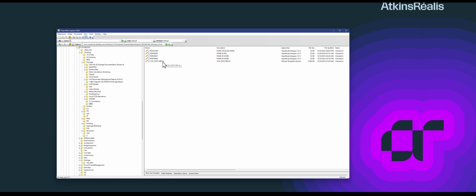And then we have an ITL. The ITL is the library template. Inside this, you have all the templates that come from FDOT, and for people who are watching this on YouTube, whatever workspace you're working on, if you're working on the default Bentley, of course, you're going to have the ITL from Bentley. And if you have the other workspaces, for example, Georgia or Tennessee or whatever, they have their own ITL. So look for your ITL.